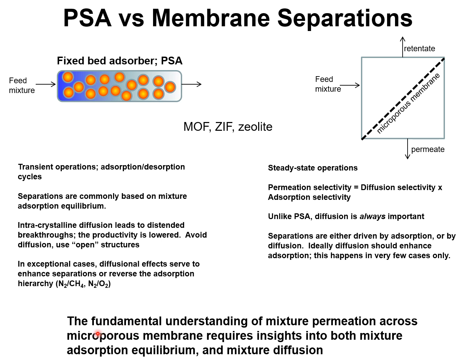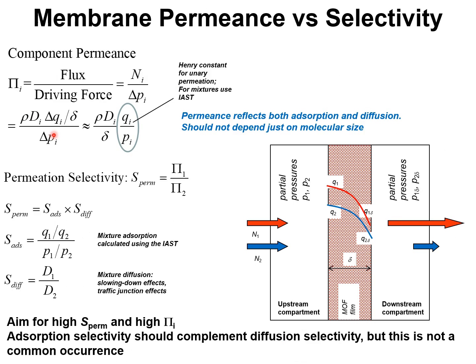And I'll leave with this general remark that the fundamental understanding of mixture permeation across microporous membranes requires insights into both mixture adsorption equilibrium and mixture diffusion. The objective of my presentation is to gain insights into the permeation characteristics of microporous membranes constructed from MOFs, ZIFs, or zeolites.